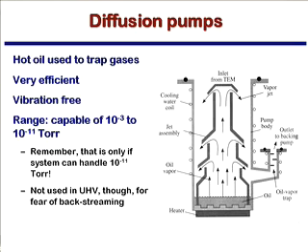Now, diffusion pumps are nice. They're very efficient. They are vibration-free, right? There's no moving parts. And so you could stick a diffusion pump straight on your column and not have it affect the resolution. That's great. The oil problem is something that people are worried about.